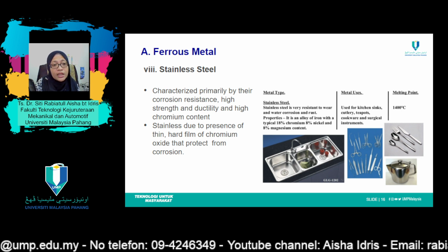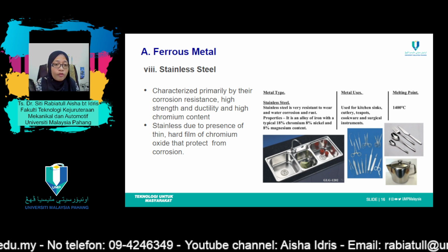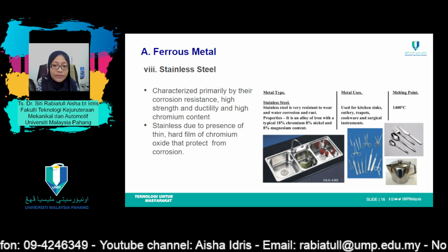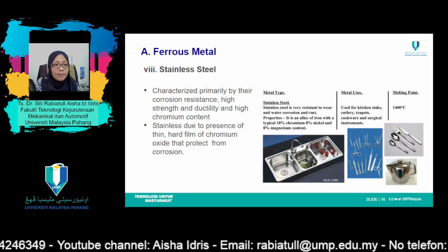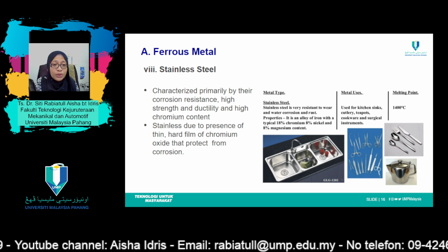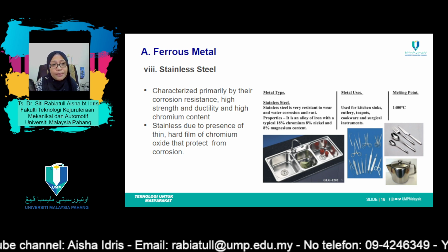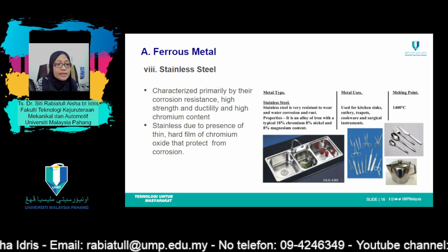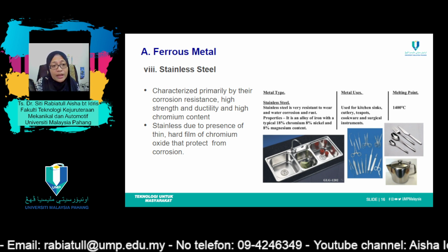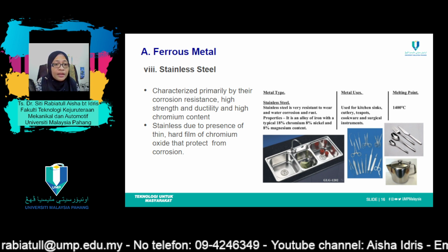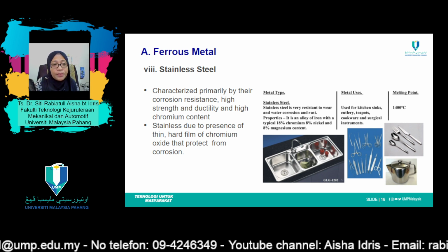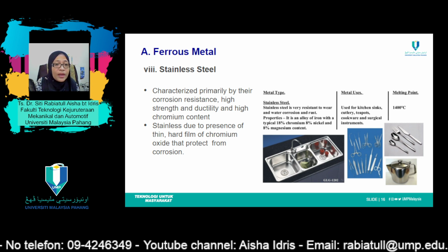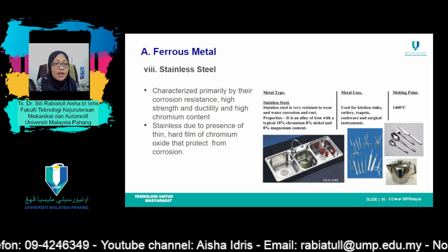Stainless steels are divided into three classes on the basis of the predominant phase constituent of the microstructure, which is martensite, ferrite, and austenite. Martensitic stainless steels are capable of being heat treated in such a way that martensite is the prime microconstituent. Additions of alloying elements in significant concentration produce dramatic alterations in the iron-carbon phase diagram. For austenitic stainless steels, the austenite phase field is extended to room temperature.